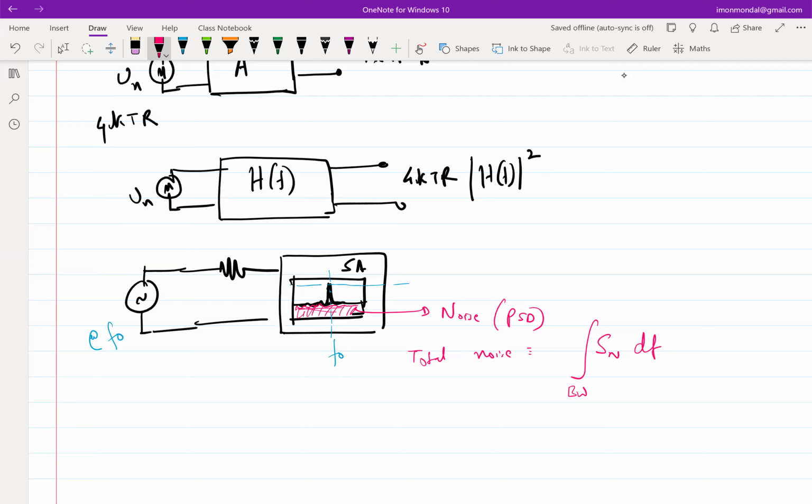Okay, but again, I am harping on the same thing. The height of this guy does not depend on bandwidth, because that's a tone. Ideally that's a Dirac delta function, right? So why is this important? It is important because if you reduce the channel bandwidth, you are going to reduce the noise, but you are not going to affect the signal if your signal is a sinusoid. So that is one way of increasing signal to noise ratio.